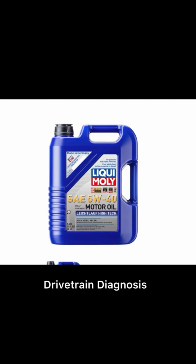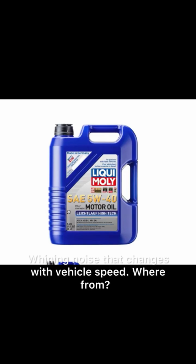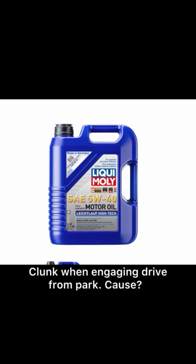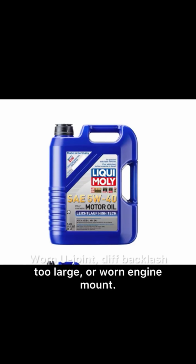Drivetrain diagnosis: whining noise that changes with vehicle speed. Where from? Differential or wheel bearing. Pitch changes with speed. Clunk when engaging drive from park. Cause: worn U-joint, diff backlash too large, or worn engine mount.